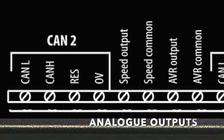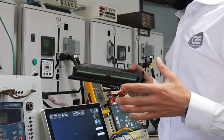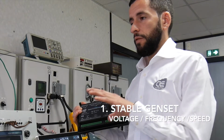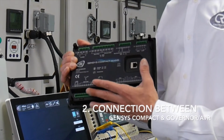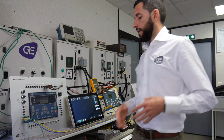It could also be an electronic engine or a pulse-driven regulation for speed and voltage. All of them work with EasyCalib. So first of all, your genset is stable in voltage, frequency and speed. You will connect the compact controller, to make the paralleling sequence, to the governor of your genset or to the AVR of your genset.